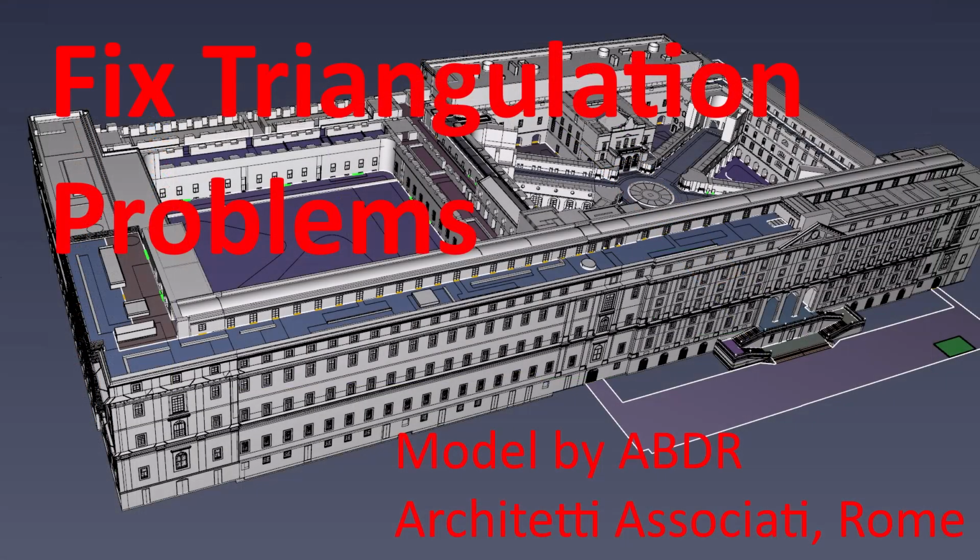So at this point, I think you understand the procedure. You basically run the model, see if there's any problems, you fix those problems, you run it again, and it doesn't take that long. Eventually, you've worked through the entire model and you fixed all your problems. What is really handy is how you can snap to, by having a room underneath and then drawing 1 meter on top. It really makes it easy to draw because it snaps to the geometry of the room below.